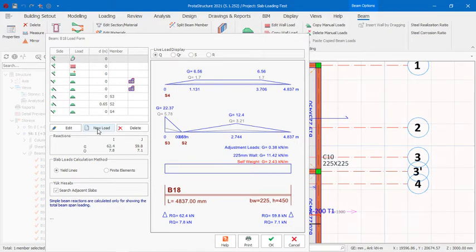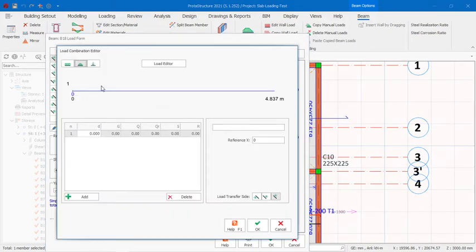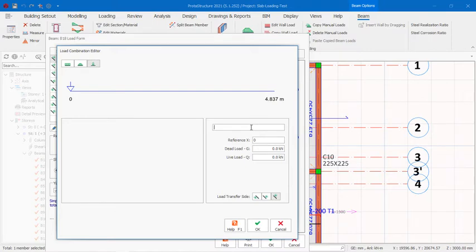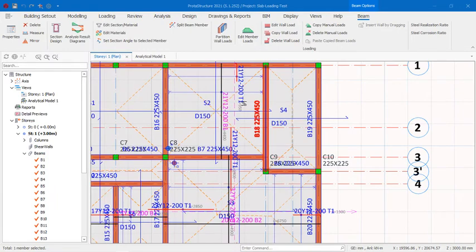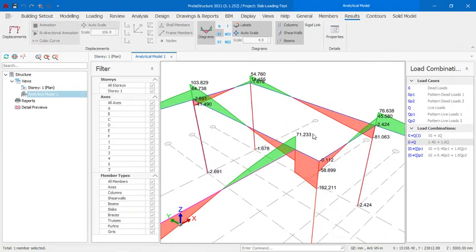will now say new load, this load, then let me say maybe like point load 1, then the reference is 650 mm, so that is 0.65, then the load is what, 71. Now you have to be very careful because that 71 we are getting from that. Let me cancel this again so that I can explain something like that. So this 71 we are getting, you have to remember that it is factored already.